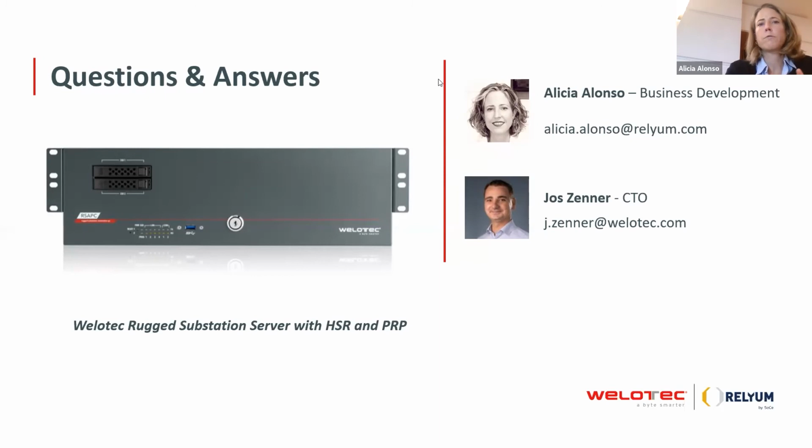Those devices, those red boxes, have to support a specific mode, because there are some modes defined in the standard. So it's a mode known as HSR PRP. So you connect the two red boxes inside the ring, and you connect one red box to LAN A and one red box to LAN B. This is the way to perform redundancy and interconnection between HSR and PRP.